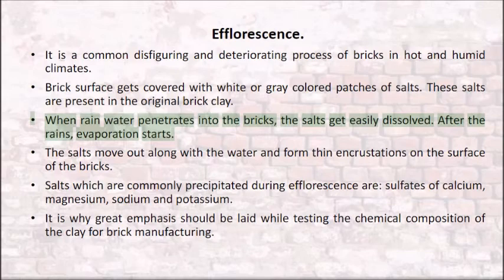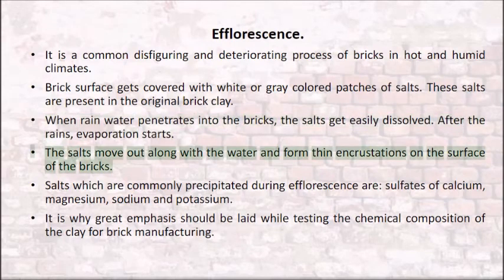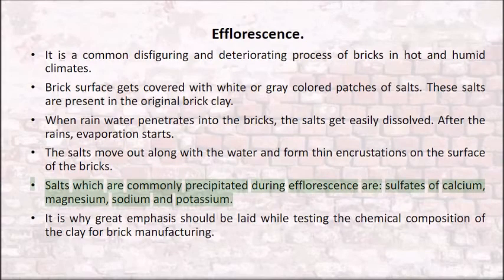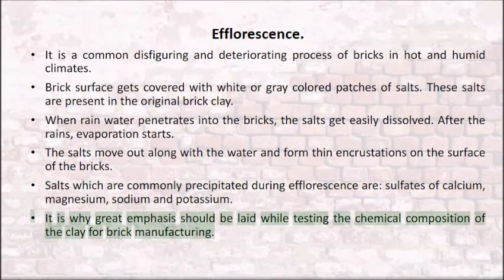After the rains, evaporation starts. The salts move out along with the water and form thin incrustations on the surface of the bricks. Salts which are commonly precipitated during efflorescence are sulfates of calcium, magnesium, sodium, and potassium. It is why great emphasis should be laid while testing the chemical composition of the clay for brick manufacturing.